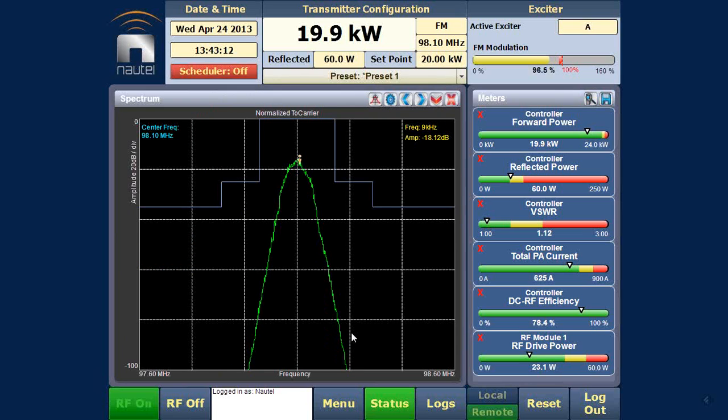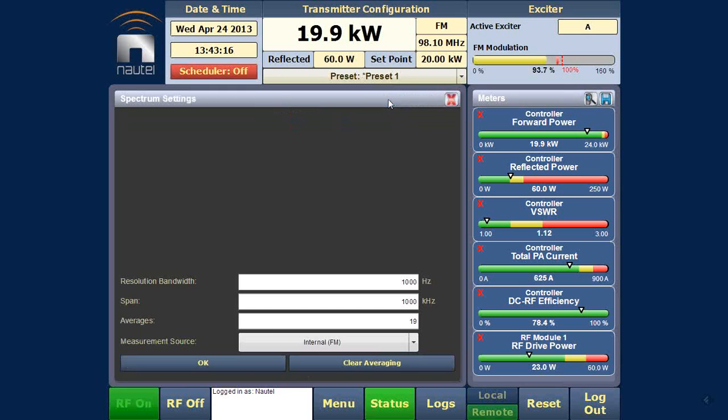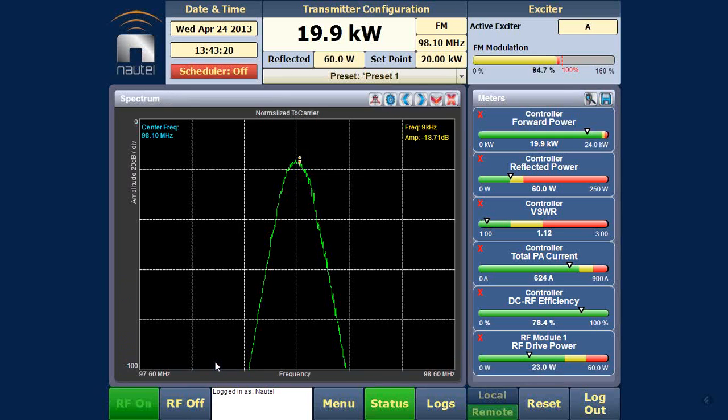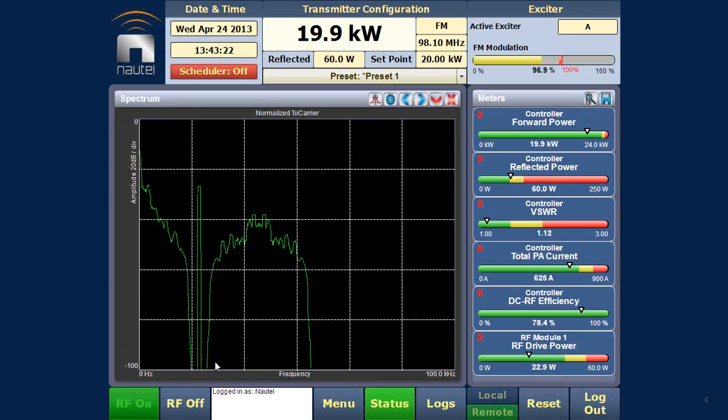And I can probe different points within the signal chain, which is really cool. This is another fun thing I can do here. I can bring up this one, and I can come over here to this and look at multiplex and hit OK, and that switches it. Now I'm looking at the baseband composite, which means that this is 0 to 100 kilohertz and 100 dB top to bottom. So there's my L plus R, my 19 kilohertz pilot, my L minus R.